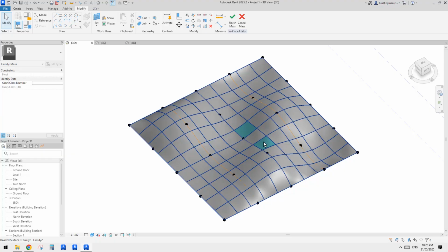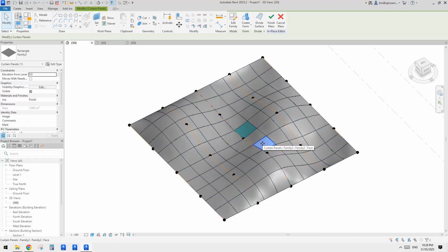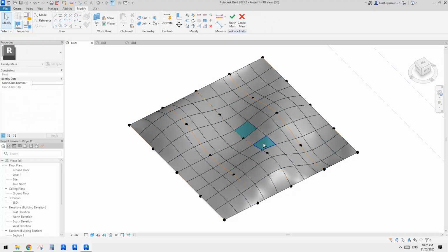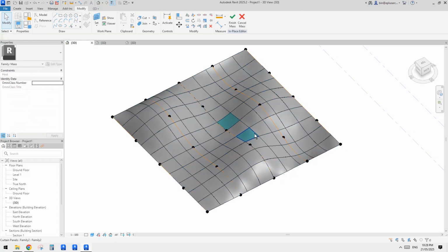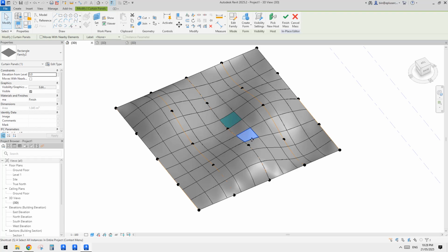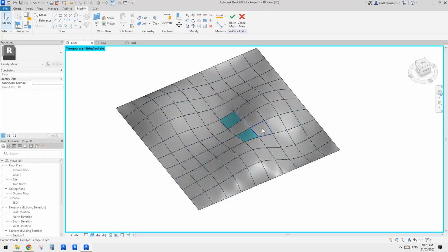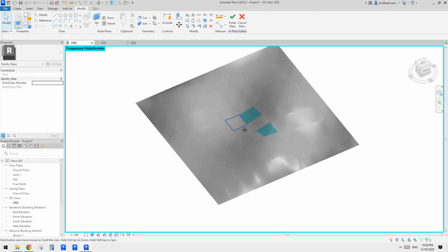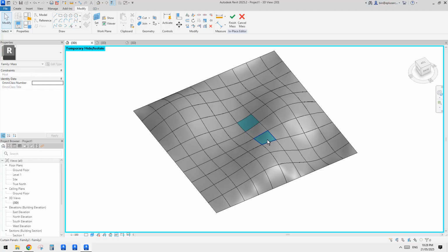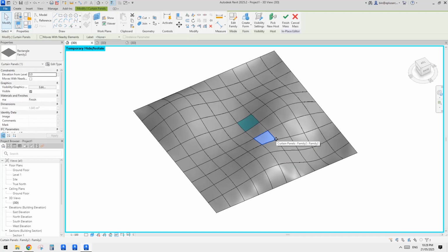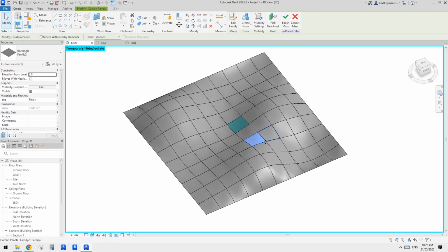Okay, so actually I'm going to just type IC. So you can tab select one of them, type IC. Oh hell, doesn't work. SAHI. Okay, so at least this one works. I'm not sure why IC, which is isolate category, doesn't work, but at least we can use SAHI. So SA is select all, HI is isolate. So isolate the selected element.